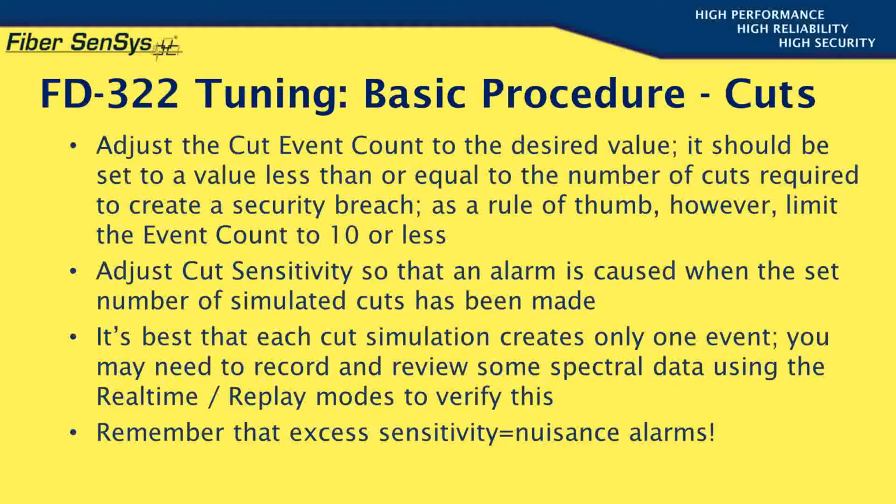Perform your cut simulations and adjust the cut sensitivity so that an alarm occurs when the set number of simulations has been made. Note that it's best for each simulated cut to create only one event. You may need to record and review some spectral data files using the tuning software's real-time and replay modes to help verify this. Once again, remember that excess sensitivity equals nuisance alarms.